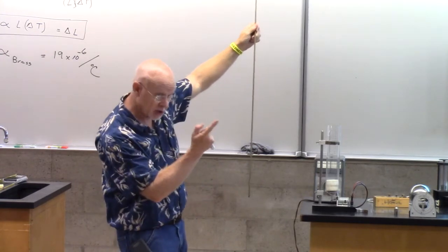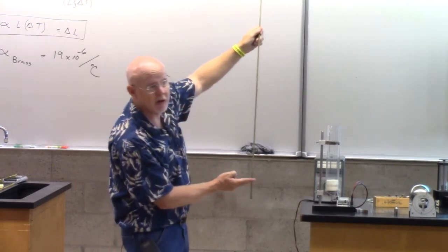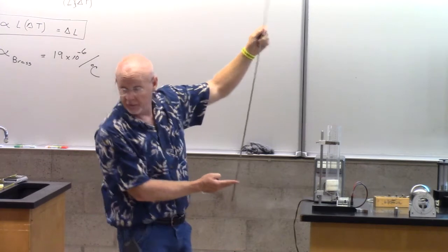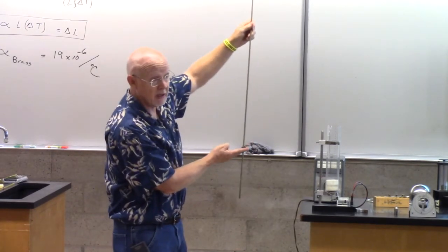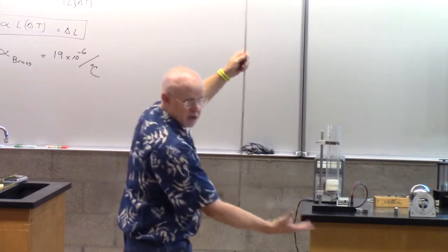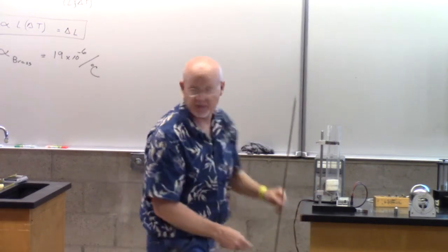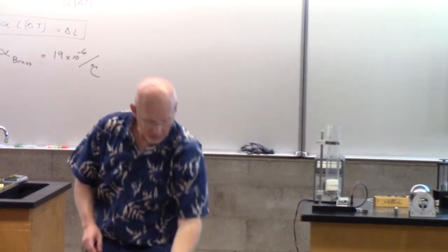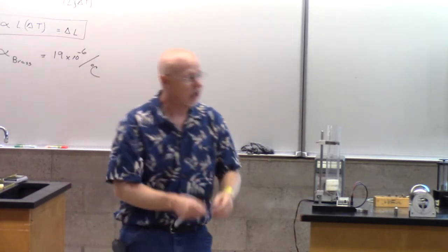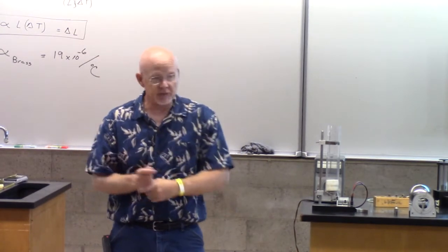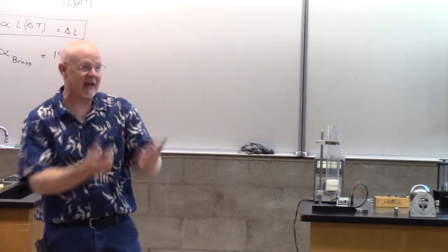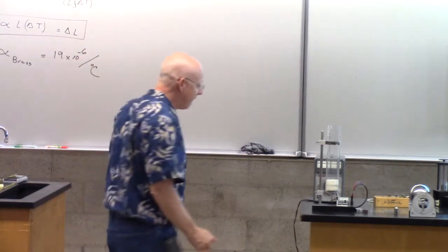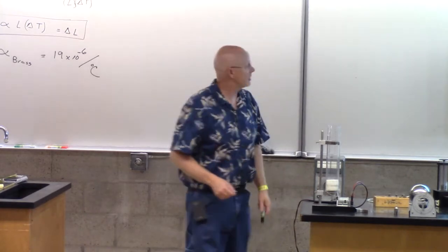And if the transmission is cold, there's a little mark here that says this is where it should be when it's cold. But if you've been driving that car for a while, if your transmission is hot, this is where it should be. The transmission fluid is now taking up more space. And so to get the correct indication, you've got to have the right volume. To get the right volume or the right size, you have to know what the temperature is. And that's what I'm getting at here. And so our first thing is a little thermal expansion.